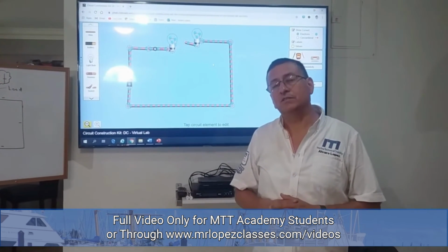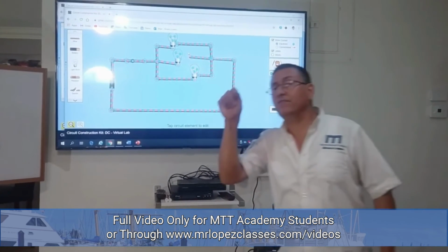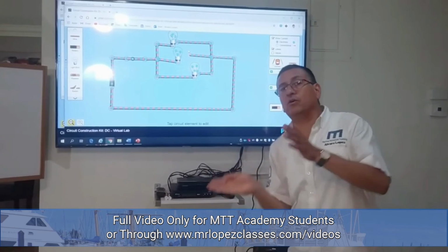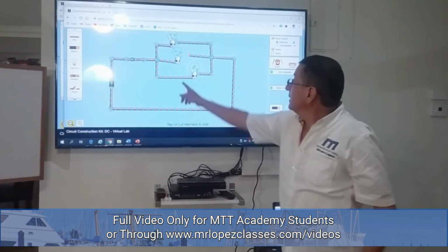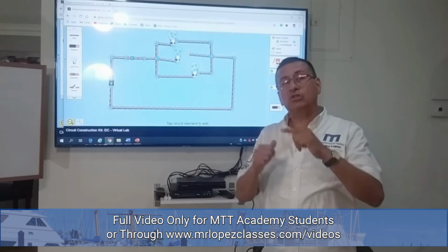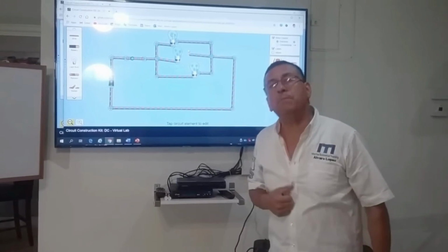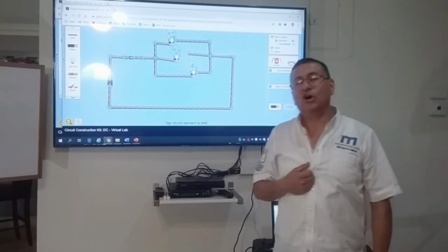This is the inconvenience again. If I have a parallel circuit, if one of the elements is broken, the current continues through the other path. This is better. In that case, a good recommendation is to install those bilge pumps in parallel, not in series.